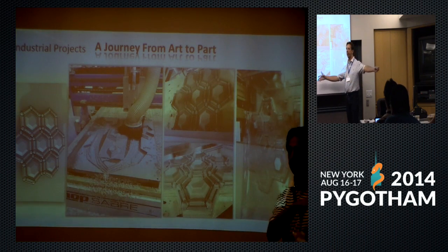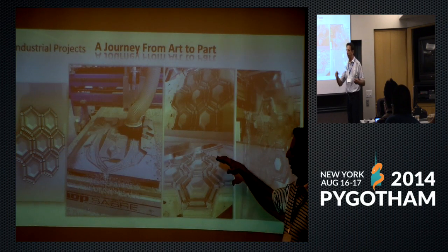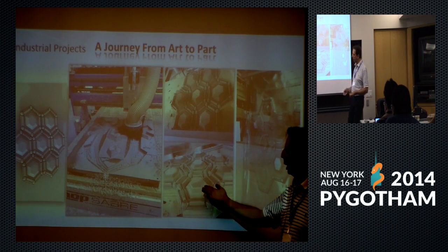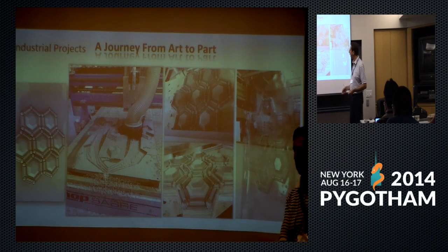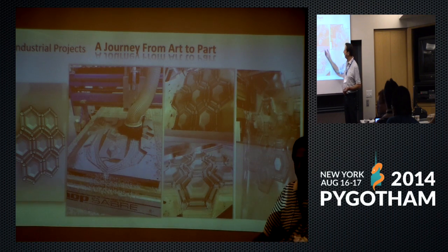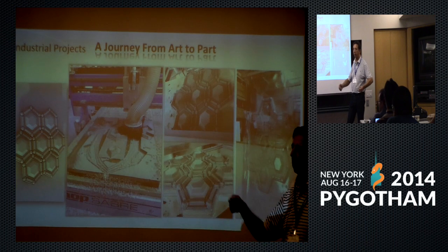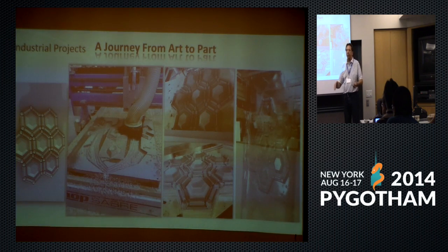It's like a big panini press. That sheet is suspended from above with elements. And when it reaches a certain temperature and it's quite limp and puffy, the part here is lifted towards it. The sheet is set down, is applied, and this sheet is sucked to the shape of this. It is cooled down quickly with pressured air, and then extracted.